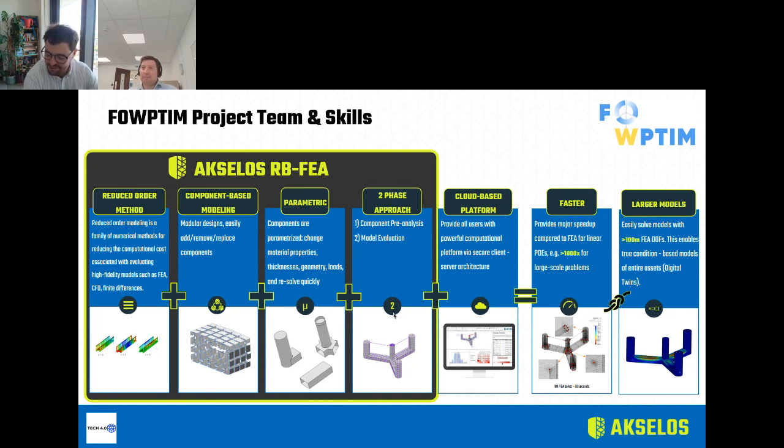So what's different with Akselos models? I think the key takeaway for Akselos models compared to conventional models is that we can get FEA simulations in 1,000th of the time of conventional FEA. And how do we achieve that? It's the slide I'm presenting here. But what it means in terms of the user workflow is actually not much different. There are some specificities like componentization, which are different from what tends to happen with Abaqus or ANSYS. But other than that, the workflows are similar.